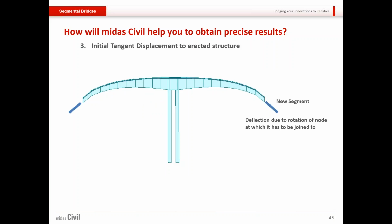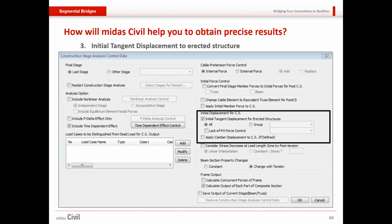The software also has something known as initial tangent displacement for erected structure. So for a FCM bridge, say it has already a downward deflection. So the new segment would be added with that already initially rotated part, and that displacement would be taken up. So that could be done by simply activating this small tick mark over here, and the software will consider that for the analysis part.